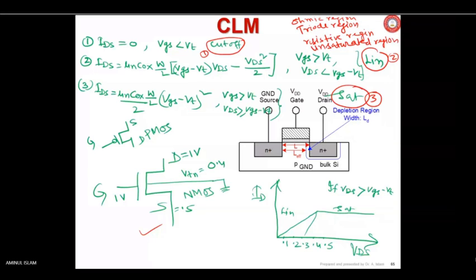The amplifiers you are going to discuss will always be considered in the saturation region, and why can be discussed later on. But for your information, all the amplifier MOSFETs are operated in the saturation region because gm is higher. What is gm? You don't know, I don't expect that also. But can you tell what is the... Sir, yes? It is working in the saturation region. The saturation region condition is known. Let us check.